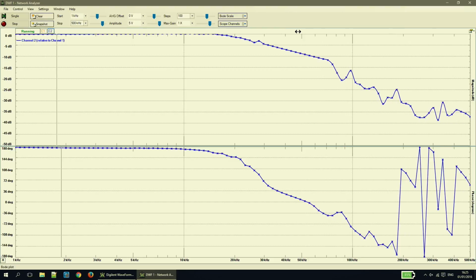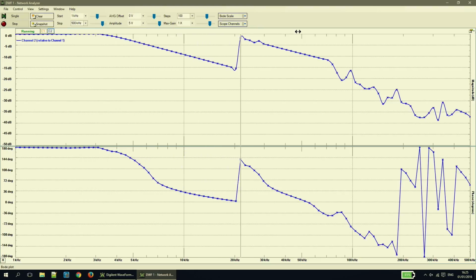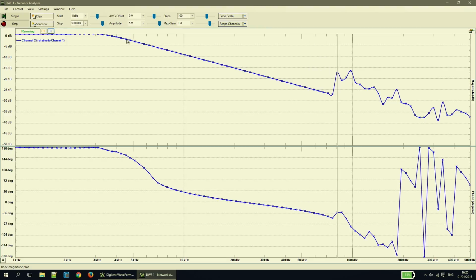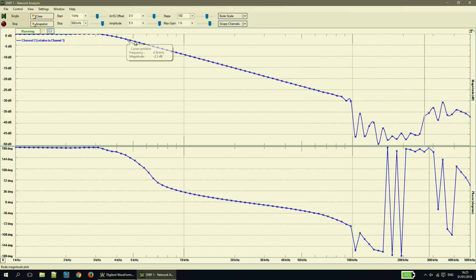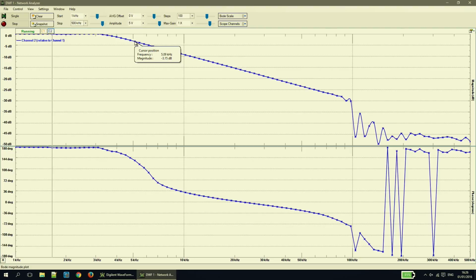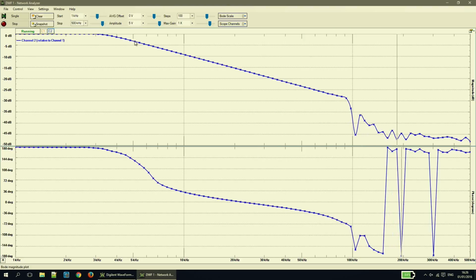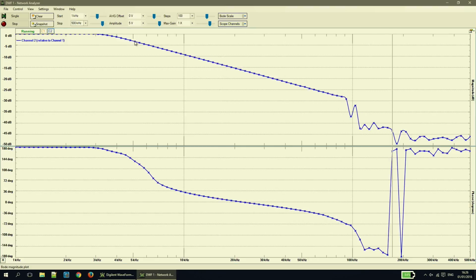And let's bring our 5 volts down to 1. And if we just measure that cutoff frequency again, there we are, about just over 5 kilohertz. So from 10 volts to 1 volt, we've got 1 decade of change on the cutoff frequency. It's working very well. What it does illustrate, though, is that if you try and put too small a voltage in, you're going to end up with very high precision required to really get an accurate cutoff frequency.